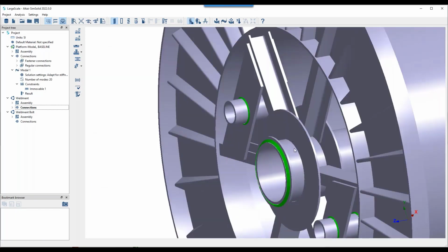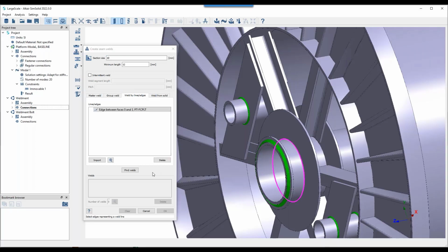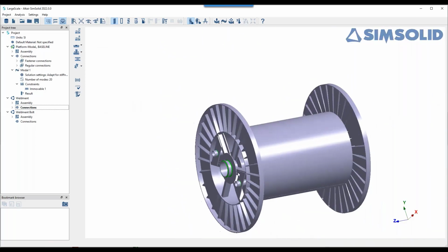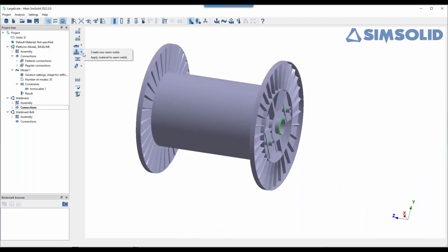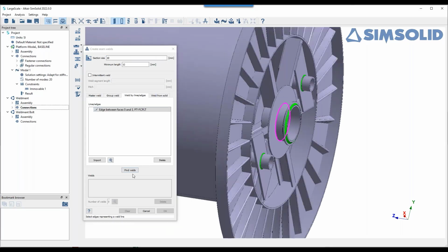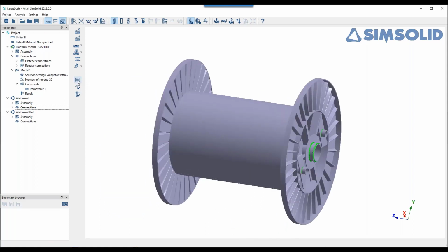And then we're going to put a weld here between this plate as well. So we can do that by an edge. Oops, I keep forgetting, you need to do the same thing on the other side. Weld from line. So hopefully we have created the connections using the weld as an option, not the actual contacts. And let's check if everything is connected. Okay, the assembly has no disconnected group of parts, so everything looks okay.